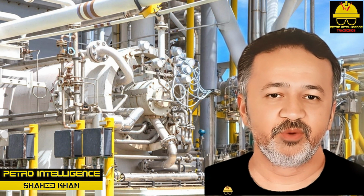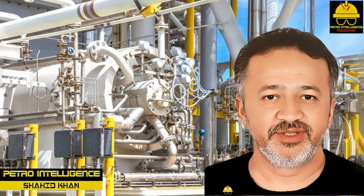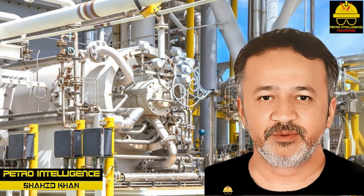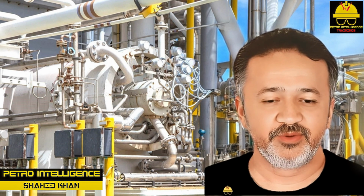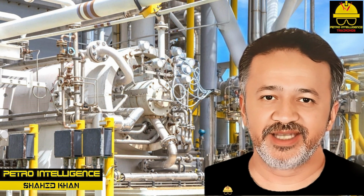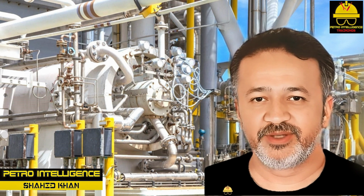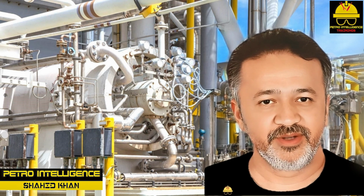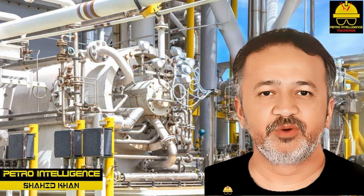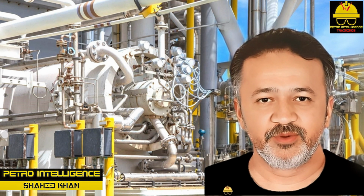Multi-stage compressors, with cooling between stages, are used to develop high pressures to allow for the heat of compression. The compression ratio normally runs in the 3 to 4 range, with the same approximate compression ratio in each stage. For example, if the desired discharge pressure is 1,500 psia, a 4-stage compressor with a 3.2 compression ratio in each stage might be used.